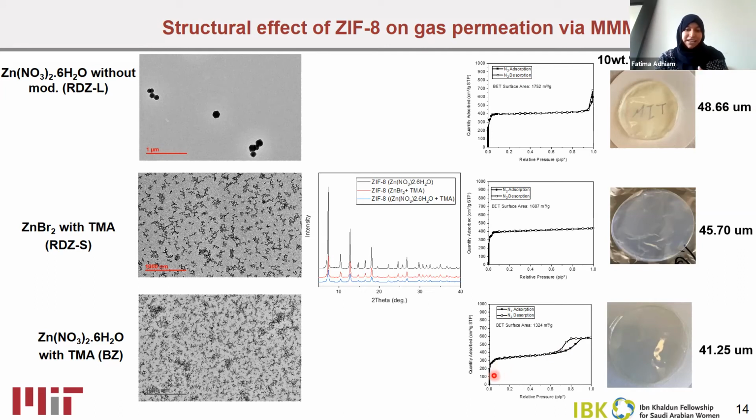So before that, we have here the same behavior of the isotherm type 1, which indicates the presence of microporous material. However, the presence of this behavior, which we call the hysteresis loop, indicates the presence of a larger pore size, the mesoporous material, which is larger than 2 nanometer up to 15 nanometer. And from the shape of the hysteresis loop, we can predict the shape of the pore itself, and this is type 1, cylindrical pore shape.